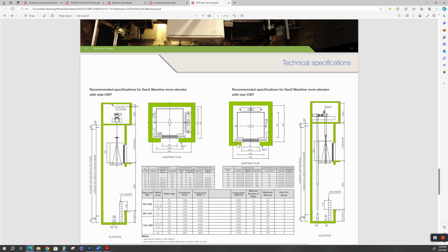But your structural engineer will have to supply the hoistway at the proper dimensions for the hoistway. And if you have a motor room on top, they'll have to do that, et cetera, and your structural engineer is going to want to use this as a shear column, much like the pagoda pole, depending on the geometry of the building.